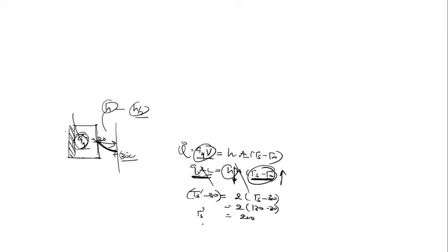Then Ts dash is equal to 200 plus 30. It means it becomes 230 degrees Celsius. So yes or no? Tell me please. Which was initially 130, now becomes 230, because the temperature difference has to increase by twice to keep the same amount of heat removed. Is this clear?